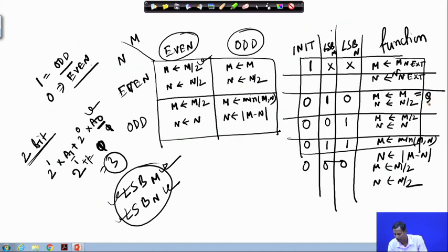That means here q i will be the q i value. And whenever it is by 2, q i will be q i plus 1. That means just discard the LSB position. Then this I require as the other input or other function. I need other circuitry to produce the minimum of m and n and the mod of m minus n. So, this is the operation table.